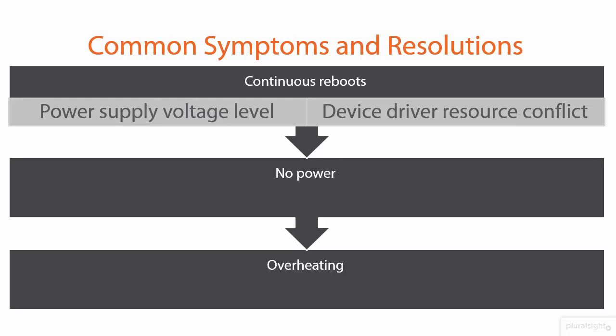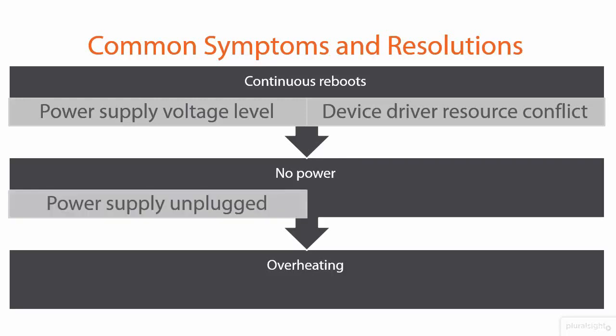How about no power? Just no power at all. Let's assume, layer one, that the computer is plugged into an AC receptacle that is hot, that is live. You want to consider, is the power supply unplugged? Specifically, remember the ATX connectors on the motherboard. Those are going to be biggies. And you'll also want to look at connectors, Molex, PCIe, Berg, whatever, that are powering the other devices.